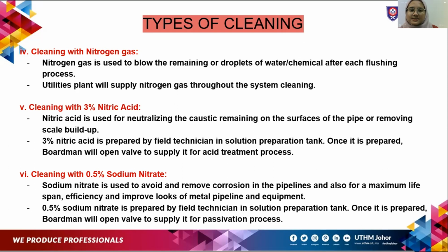Next is cleaning with 3% nitric acid. Nitric acid is used for neutralizing the caustic remaining on the surface of the pipe or removing scale buildup. 3% nitric acid is prepared by the field technician in the solution preparation tank. Once it is prepared, the boatman will open the valve to supply it for the acid treatment process.